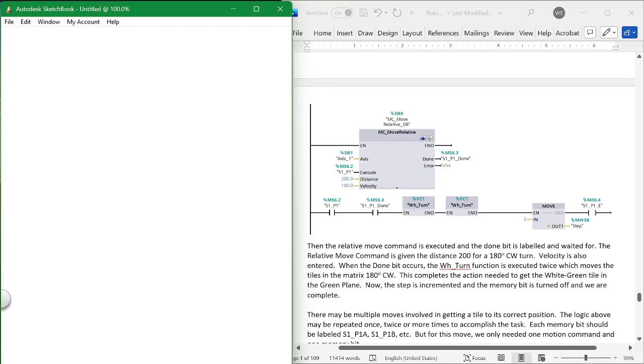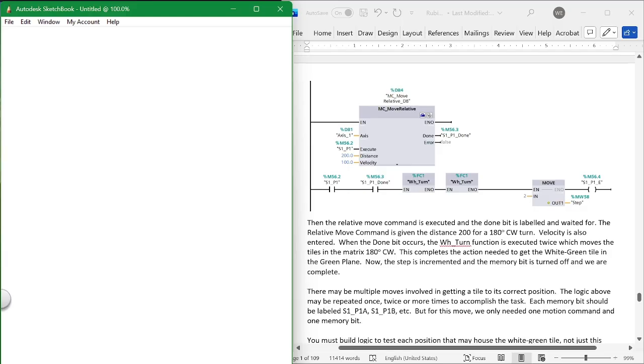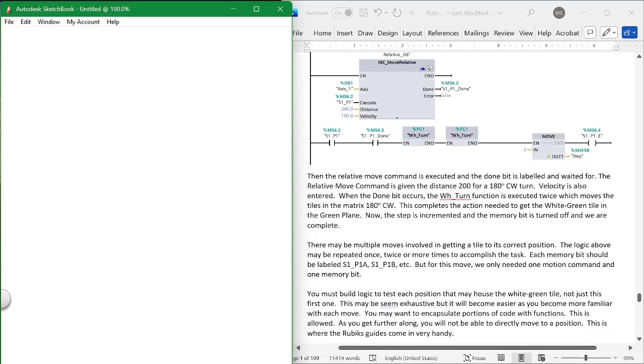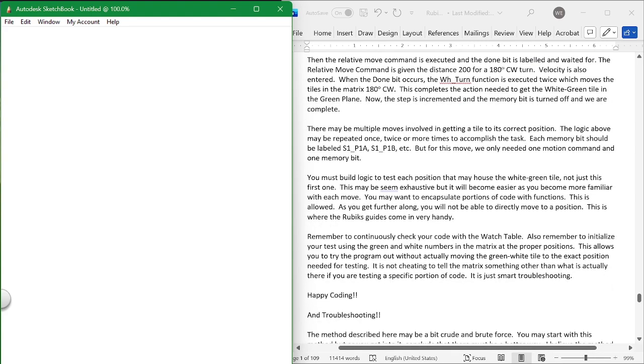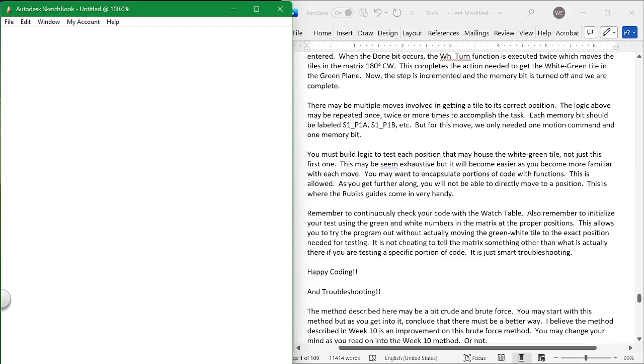Now, after each of those, you want a little time delay to go to the next one. So there should have been a timer here as well, a time delay to then move to the next command. So this is a pretty burdensome way of getting a project like this done. But it will work, and that's what actually happened with the first group that did it.